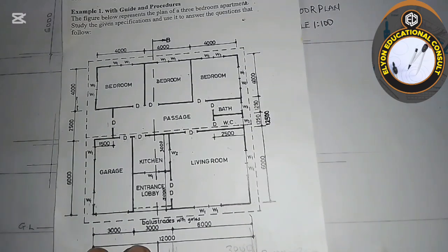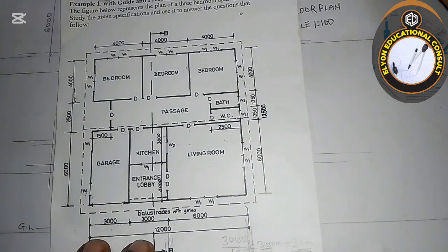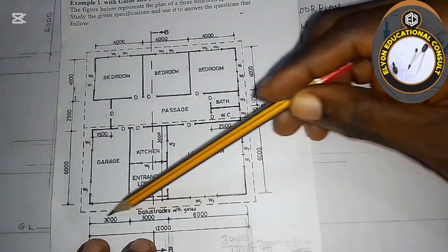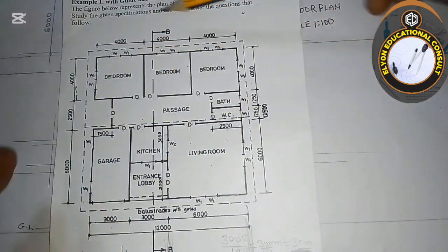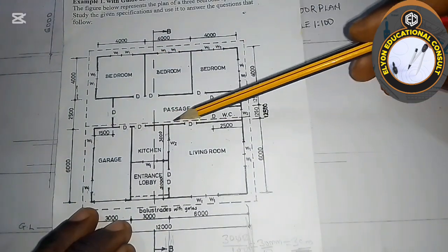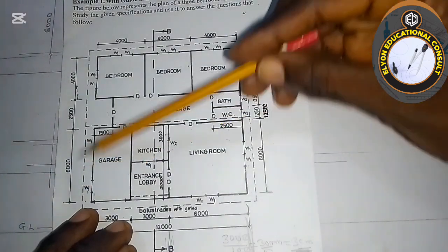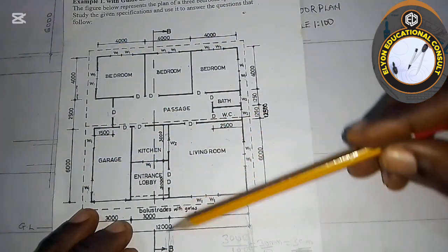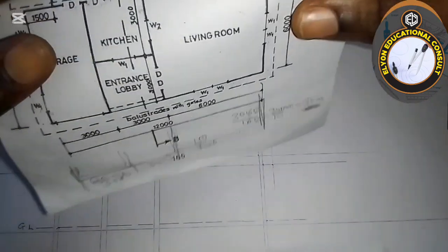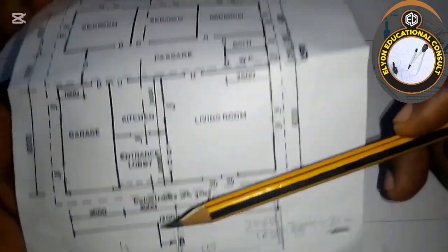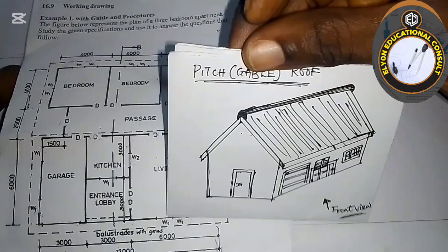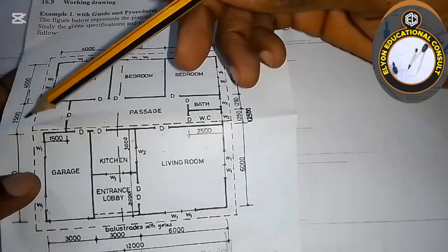If you look at the floor plan, you can see this area here, the whole of this dotted line here. I hope you can see all of this dotted line. It means the roof that is covering the building. Why this inner line here demarcating all of this part, to this side and to this side, that is the pitch roof. Okay, it's like you are having the roof like this. This is a sloping side, this one sloping side, this is another sloping side in this format like we have here. So this is where the ridge cap is on.